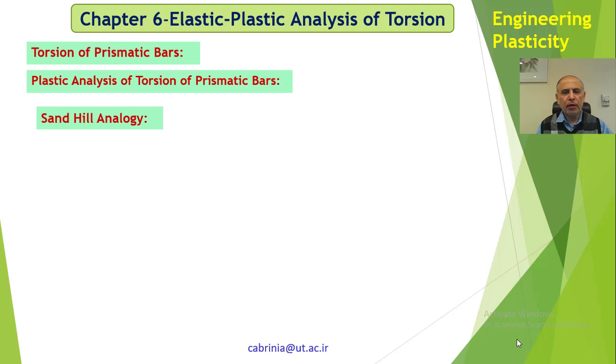So far, we have talked a lot about the torsion of prismatic bars, but all of what we have said has been concentrated or focused on elastic analysis of prismatic bars. Although we elaborated on many different and interesting techniques, they have all been for the elastic analysis. And here we are going to present to you plastic analysis of torsion of prismatic bars.